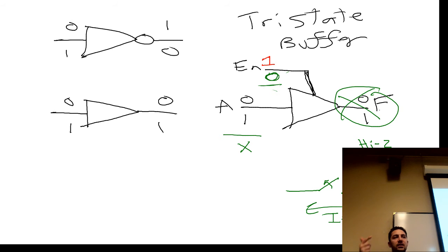So if you accidentally left one of the pins of your 7400 unconnected, it would float because it has no connection to either high or low. And the weird thing about floating is the chip is going to interpret that either as a 0 or a 1. It has no choice. It has to resolve to one or the other. So your chip, when you're using it, what do you think it's going to float to? Is it going to float high or float low?